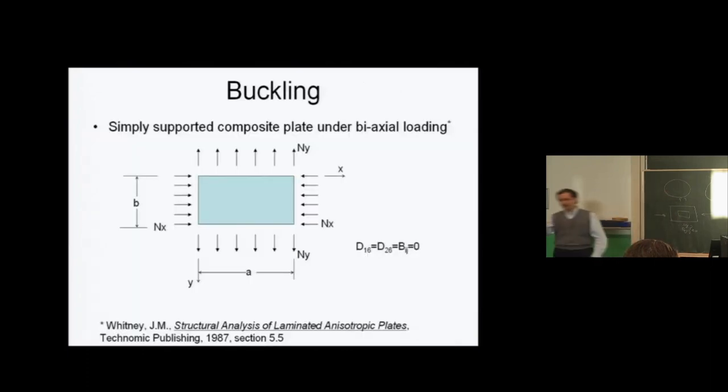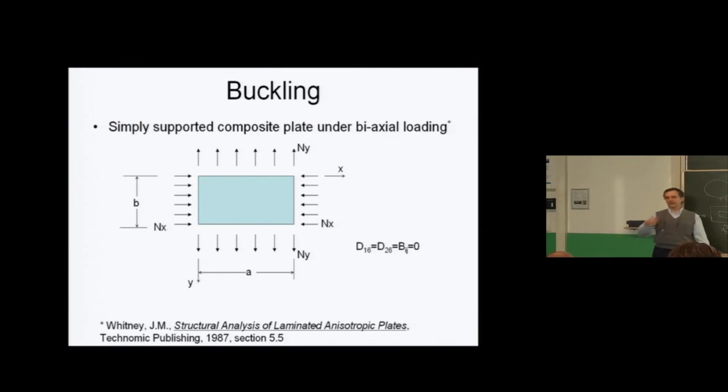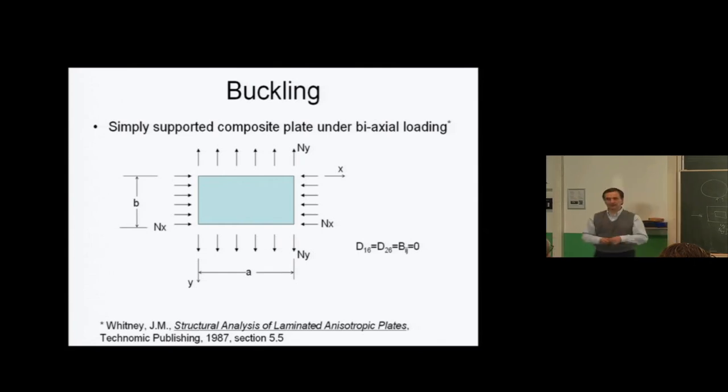So buckling, it happens very often. It's a very common failure mode. In fact, most aircraft structures are designed for buckling, or the percentage of a structure designed by buckling or stability-related requirements is much larger than anything that's failure-related, except potentially for damage tolerance, which is the second most common failure mode that designs structure. And if you are careful about it, you can actually use it to your advantage and save weight when you do post-buckling, and we'll talk about post-buckling in either the next lecture or the lecture after.